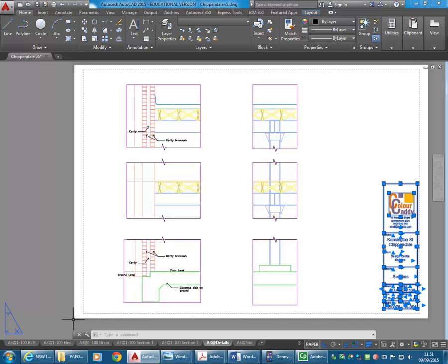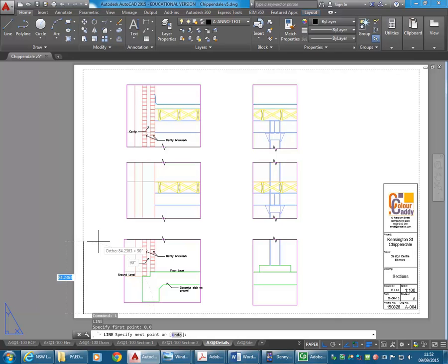Yeah, it's the origin. So on a page, it's the corner of your page. Normally, if you're working in model space, it's the absolute origin. If I draw a line from 0,0 here, notice, it's actually from the printable area, so from that dashed border.